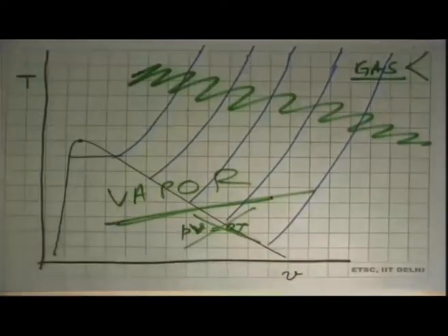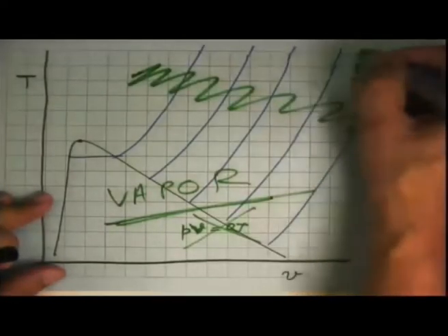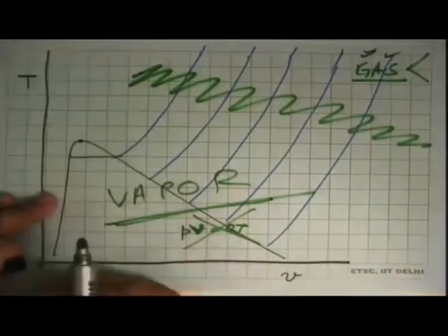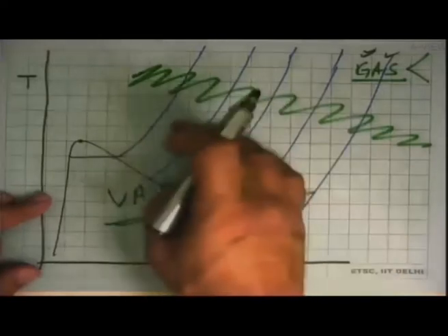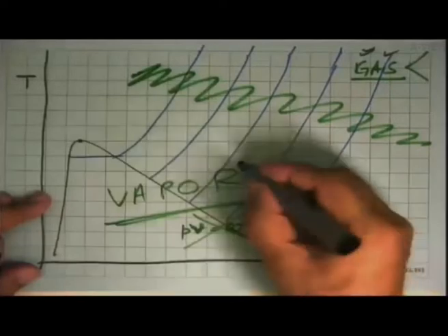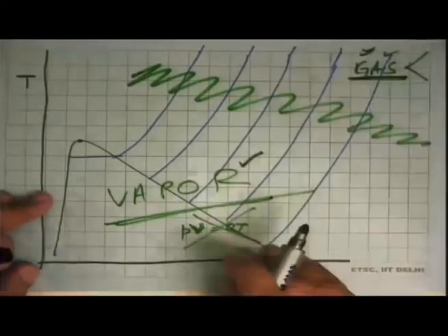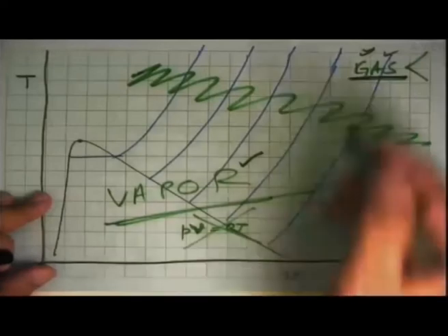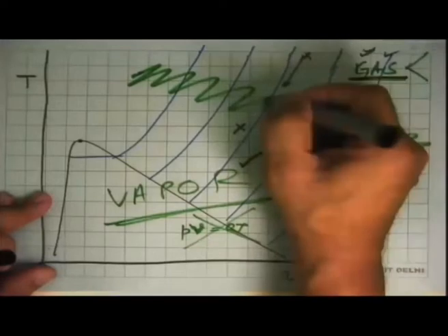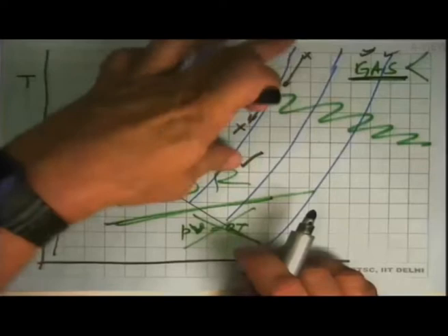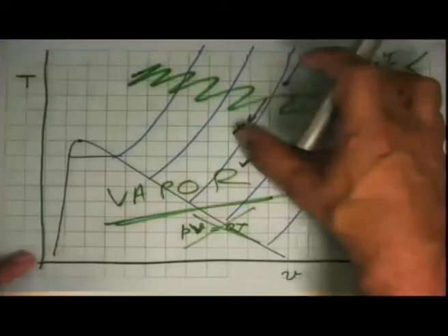And as I mentioned yesterday, we have several applications where you have the application entirely in this region. So we don't even come into this part. And then we have applications which are entirely in this region, maybe sometimes touching this region, but largely in this. So those have to be treated as vapors, and those other cycles have to be treated as gas. And those few examples where you have some behavior here and some behavior over there, we then have to do a mix and match and very carefully see how properties get added up to give us the total change between this state and this state.